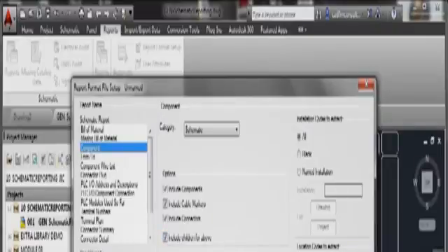I can save the report to a file, change the report fields, put it on the drawing, and sort the fields that way, so I can automatically put it on the drawing if I want to. My installation codes to extract and my location codes to extract, I want all of them, or I can leave it blank, or I can have a named installation. I can sort by drawing or project as well.